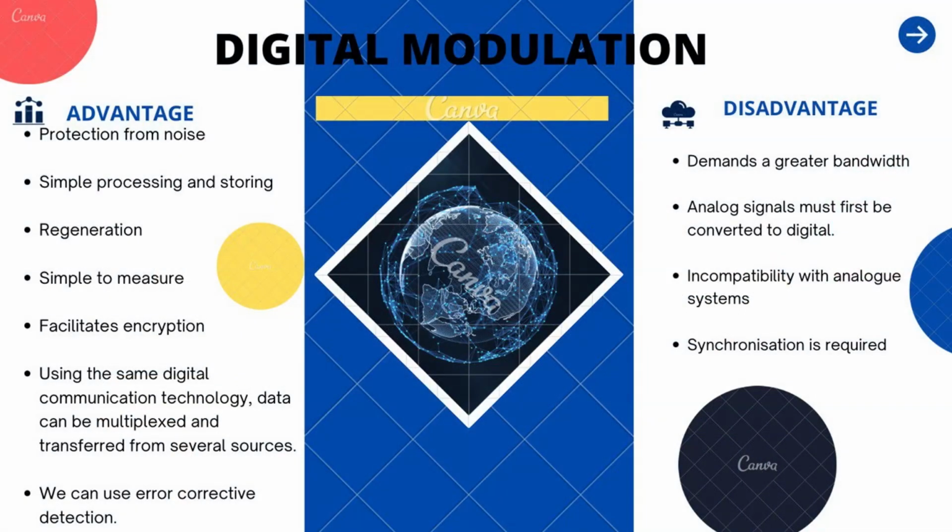We go through for the second part, that is pulse modulation. So, in our world now, information signals must be changed to digital form so that they can be transmitted through this network. So, there are several techniques requiring full coding of the original signal used. There is pulse code modulation, PCM, differential PCM, DPCM, adaptive differential PCM, ADPCM, delta modulation, DM, and the last is adaptive delta modulation, ADM.